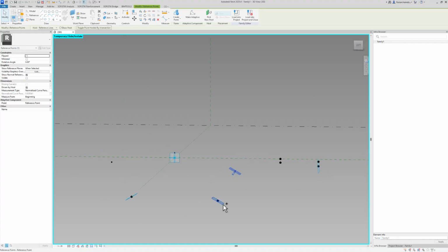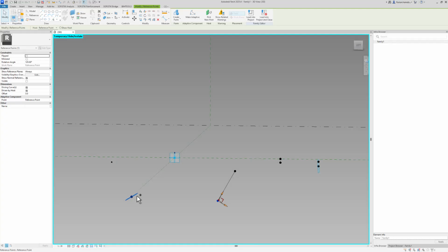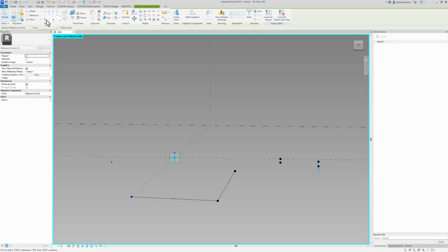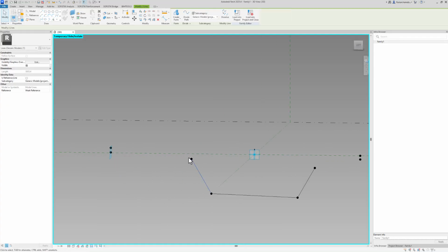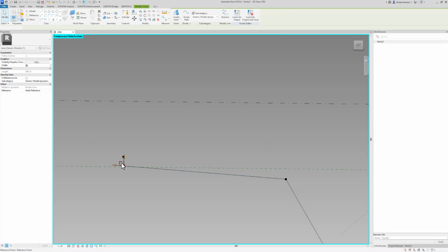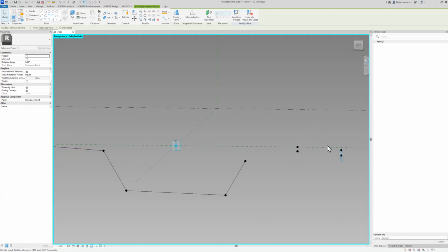Now I can select the points and create new reference lines or new model lines. These model lines will then be used as the geometry for my superstructure command. Be careful not to select too many points. You can only select 2 points and click on spline through points for the program to properly recognize the intersections. Meaning, for example, here I have 3 points in one point. Make sure to only select one of them by left clicking.